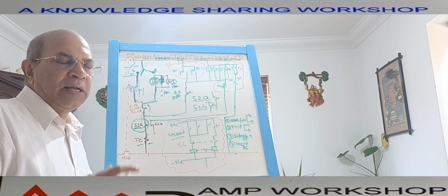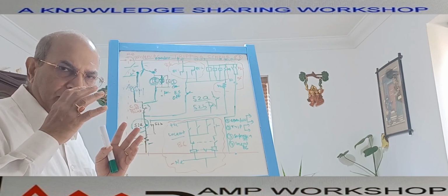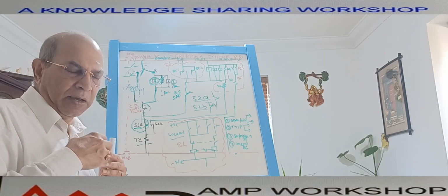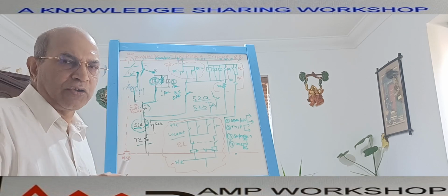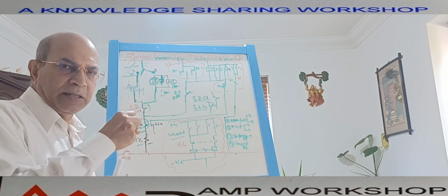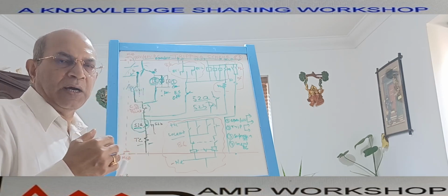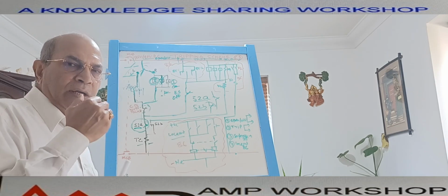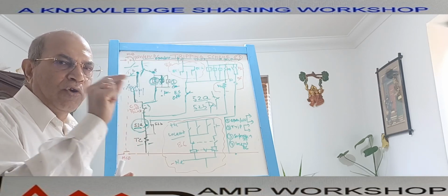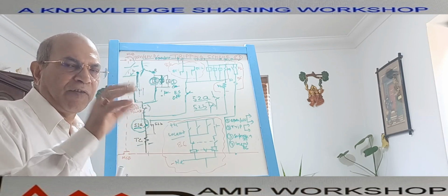In one digital relay, there is an input card and an output card. Output card means when the relay analyzes, computes or calculates that there is an extra high current or some other abnormal voltage or abnormal current in the circuit, it can measure and understand it. Then during the design of the system, we configure the output. There are multiple output relays on this particular digital relay, and we decide which output relay will operate for which type of fault. Suppose there are 5 output relays.